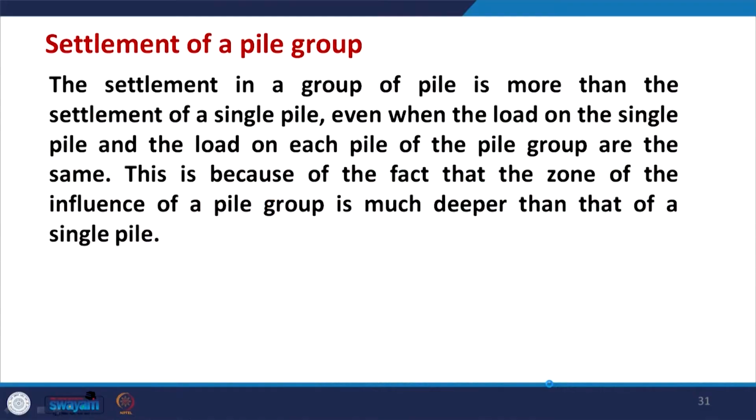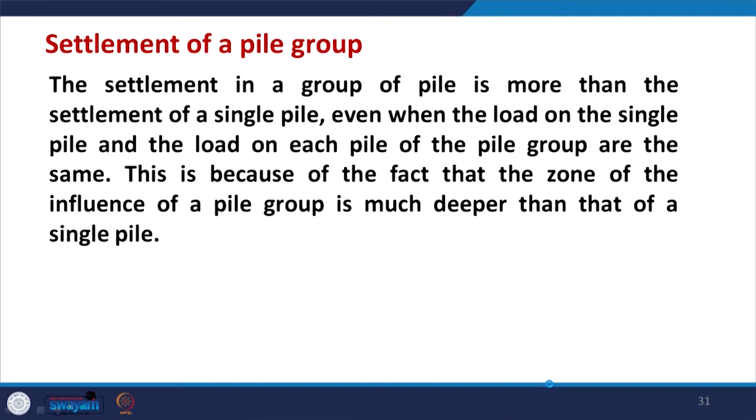Next is settlement of a pile group. This is the last theory part for vertical load carrying capacity. As we said, there are two criteria for designing pile foundations, which is the same as other types of foundation. One criterion is that there should be adequate bearing capacity, that means the factor of safety should be enough. The second is that settlement should be within the permissible limit, and normally the settlement of a pile group is more than the settlement of a single pile, even when the load on the single pile and the load on each pile of the pile group are the same.